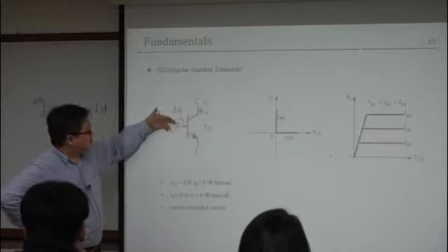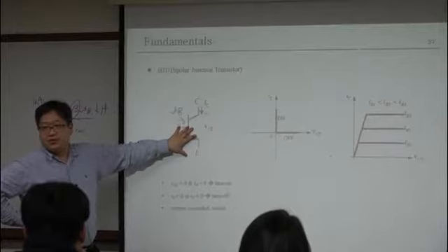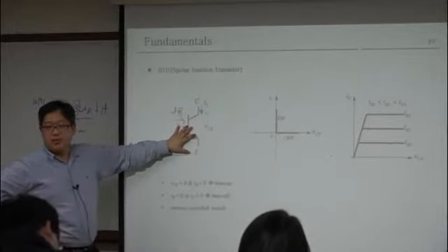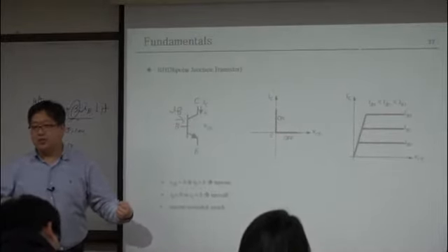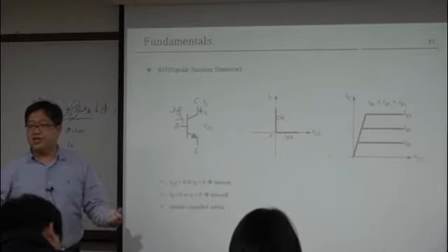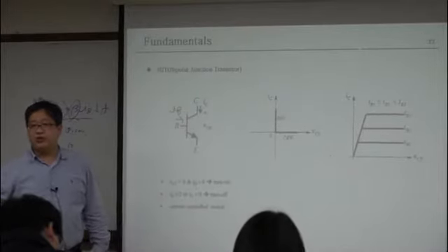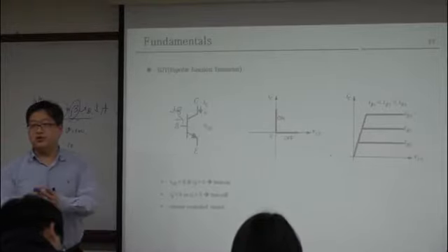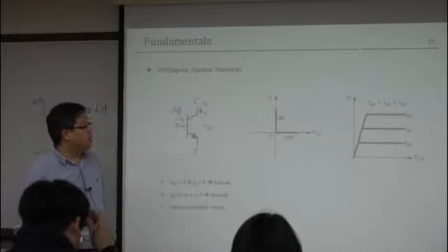So the BJT's efficiency is not very good. If your efficiency is bad, then you should have a giant heat sink, right? Low efficiency makes large thermal. Then the heat creates switch failure. So to cool down the temperature of the switching device, you should have a very giant heat sink.